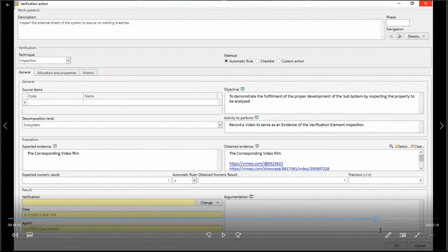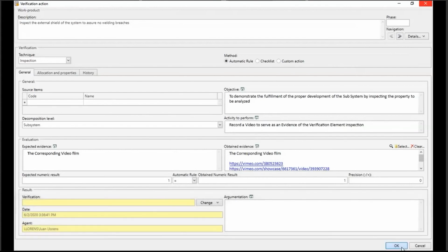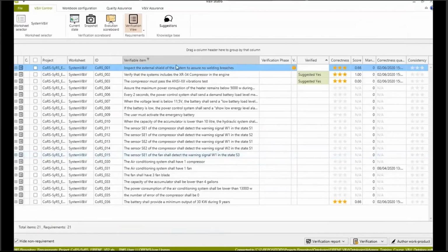So what they do is put a camera on a specific, very small train, and then they traverse these 200 or 400, I don't remember, kilometers of railway, recording what they see. Then the software analyzes the camera footage, identifying the different elements, typing them, counting them and bringing them back. So this is automated, and the verification process is automatically done, including the evidences.